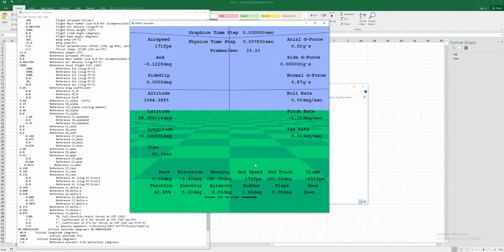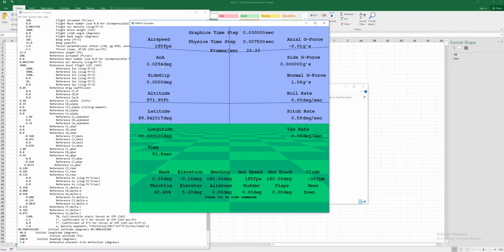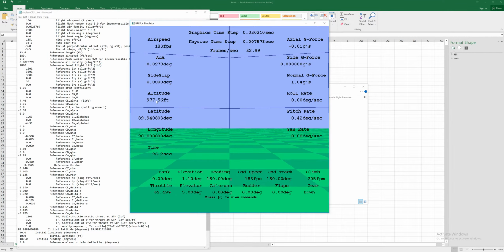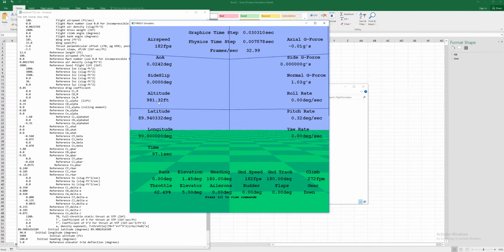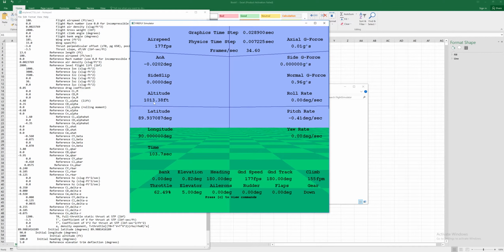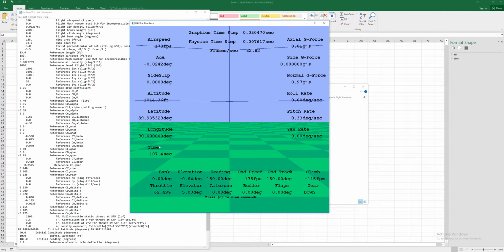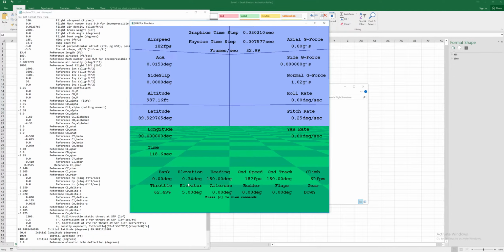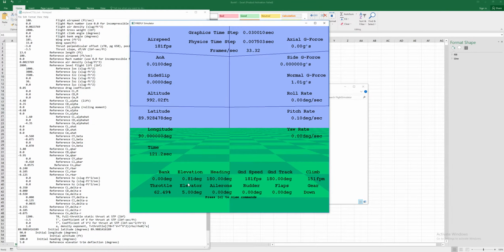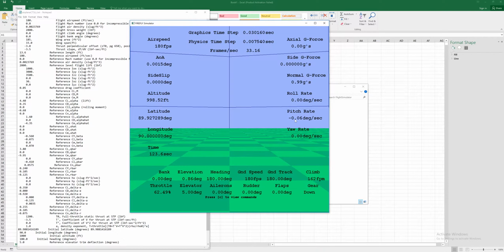You can notice a few things. So angle of attack is changing, really small numbers though. This is in degrees, so the angle of attack is oscillating, but not significantly. The altitude is oscillating rather significantly. We started off at 1,000 feet. You can see we're going up to, now we're up to about 15 feet over that. And then it's going to drop down below that again. Our elevation angle, so this is the angle that our nose is making relative to the horizon, is oscillating here up and down, and we could also have a pitch rate that is oscillating.